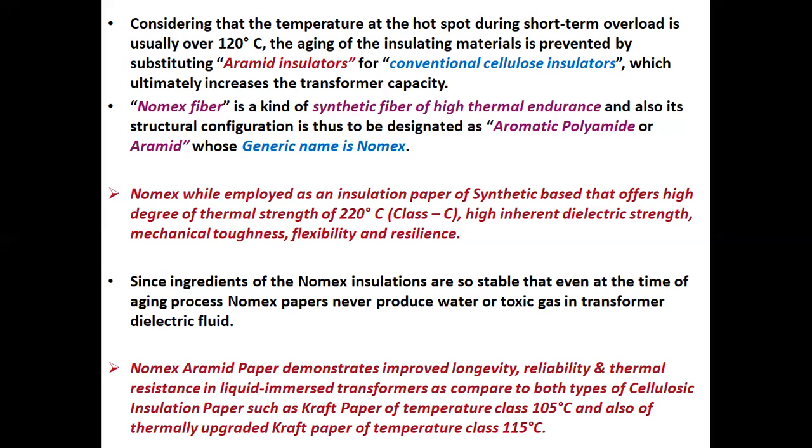Nomex, while employed as an insulation paper of synthetic base, offers high degree of thermal strength of 220 degrees centigrade, that is class C type of insulation, high inherent dielectric strength, mechanical toughness, flexibility, and resilience.